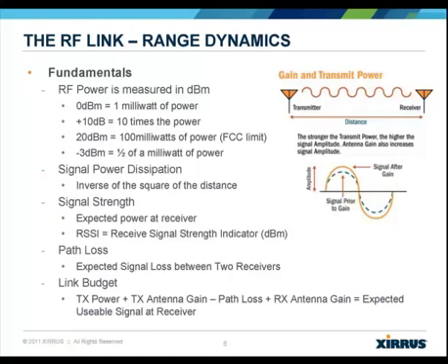As the bottom bullet indicates, your signal strength is a product of the transmit power multiplied by the antenna gain, minus the signal attenuation between the devices. This is known as path loss. The received signal is then boosted by the gain of the receiving antenna, and the signal is transmitted to the receiver. The final received signal strength will then define the actual data rates you could expect.